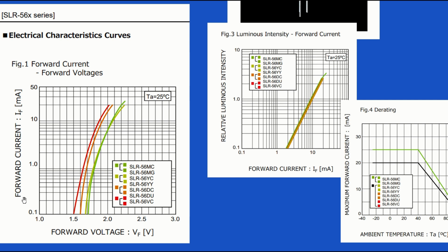So in our previous example, we said 5 milliamps. This is 1, that's 10. So 2, 3, 4, 5 is here. And if you come down, then you're right here. That's 1.8 volts. That's where I gave you that value from before. Now, it's not the brightest at